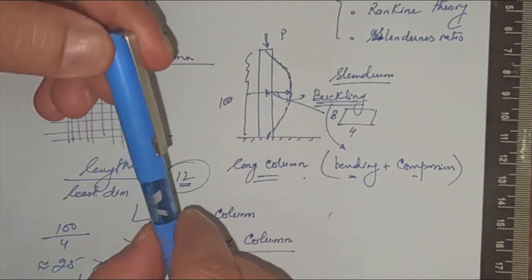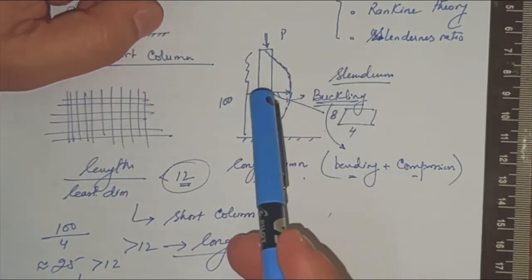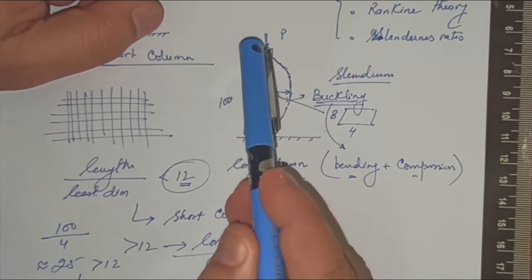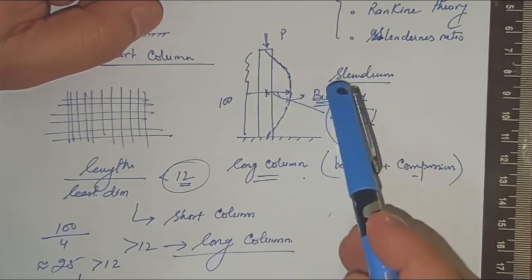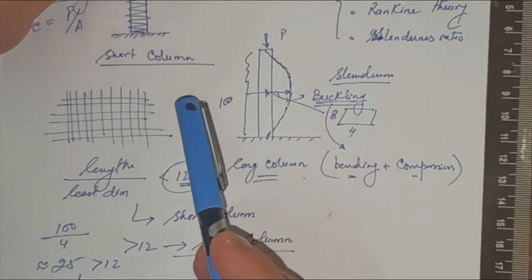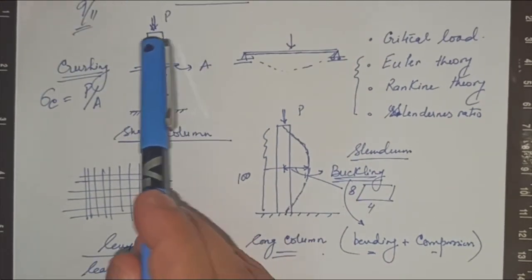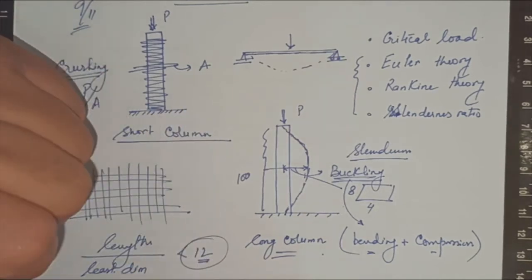However, for a higher load, if the axial load is very much higher, certain long columns buckle. They kind of dance in this fashion or in this fashion. They bend in this direction, or they bend in this direction. For short columns, crushing occurs. They are crushed like a pile of biscuits.